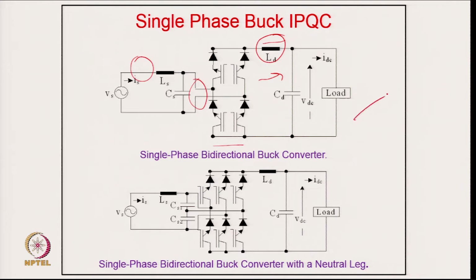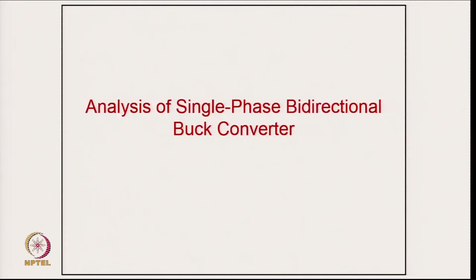So, virtually we call it a replacement of your thyristor bridge, but what is the benefit here? In a thyristor bridge you have reactive power and harmonics. Here you can eliminate the harmonics because you are operating with PWM, and the reactive power burden can also be completely eliminated because this current can be maintained in phase with proper PWM control over the complete cycle of the AC wave. And of course, this is another circuit where you use the third leg for reducing the ripple in the output voltage.